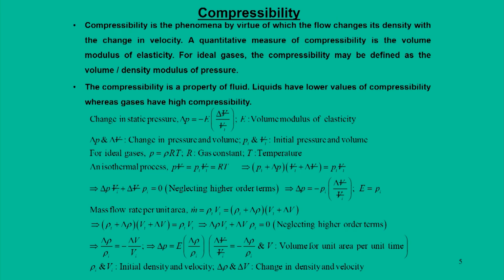What we have not touched in our previous class is the parameter that actually defines the flow changes due to the density. In our previous segments, we emphasized that density variation occurs in a flow domain, but the question remains why that density varies. For incompressible flow, pressure and density are related. For a compressible flow domain, the density can vary due to pressure as well as temperature. So, this is where the catch lies, that pressure and temperature both can change to make necessary changes for the density.